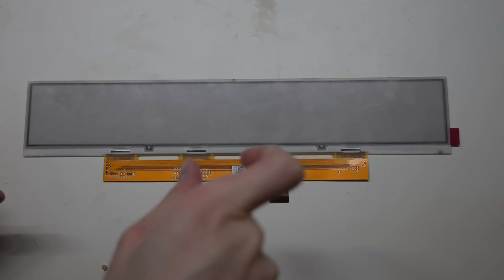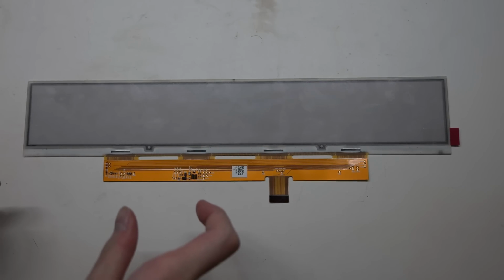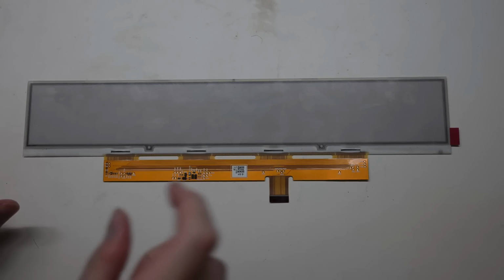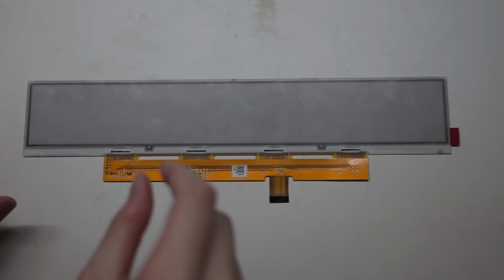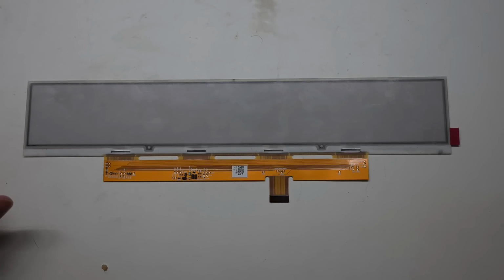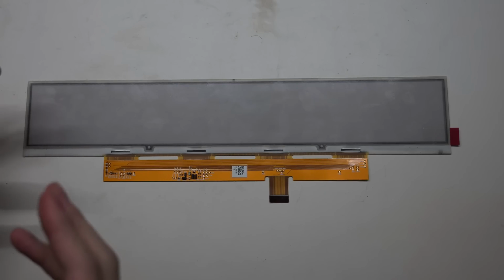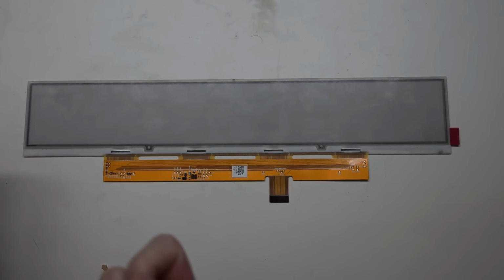That could hint it's an 8-bit parallel bus, right? Or you see only about 5 or 6 signal pins, then that's probably SPI, right? And if you can limit the pin numbers down to a reasonable number, like 5 or 6 pins you need to guess, you can also just brute force it, see which one works.